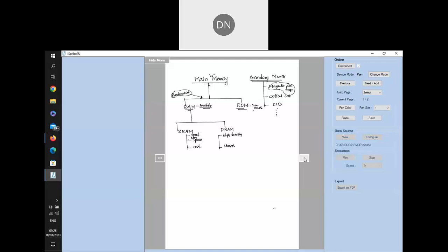In SRAMs also, there are two types of memories. If the RAM works in synchronization with the CPU clock, we know that there is one master clock which coordinates all the operations inside the processor, as we studied yesterday. If the same clock is used to synchronize the read and write operations inside the RAM, that is called a synchronous RAM. If it is not synchronized with the clock, a separate memory controller is used which generates the related control signals. Then we call it an asynchronous RAM. So synchronous SRAMs is one, and the other is asynchronous SRAMs.